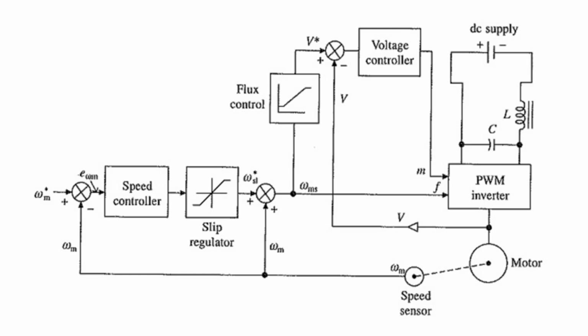The drive accelerates fast at the maximum allowable inverter current, which produces the maximum available torque until the speed error is reduced to a small value. If the speed error is reduced to a small value, the drive finally settles at a slip speed. That means it balances the motor torque as well as the load torque. That is the condition when the speed error is positive.